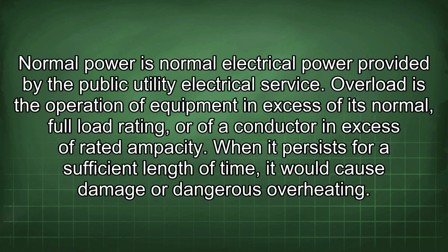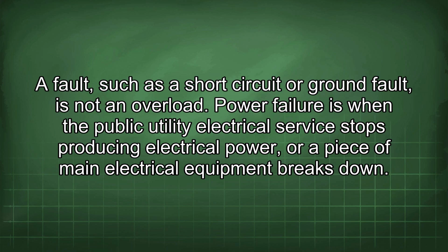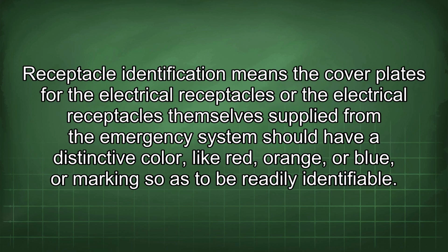Overload is the operation of equipment in excess of its normal, full load rating, or of a conductor in excess of rated ampacity. When it persists for a sufficient length of time, it would cause damage or dangerous overheating. A fault, such as a short circuit or ground fault, is not an overload. Power failure is when the public utility electrical service stops producing electrical power, or a piece of main electrical equipment breaks down. Receptacle identification means the cover plates for the electrical receptacles or the electrical receptacles themselves supplied from the emergency system should have a distinctive color, like red, orange, or blue, or markings so as to be readily identifiable.